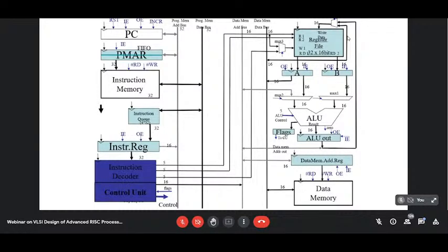Here you just notice one thing at the top left-hand side, the blue colored box, the register file. Here a number of registers are there, whereas in the CISC architecture, not many registers will be there. Okay. And another thing is, since the architecture is pipelined, your micro-operations flow will be slightly different.